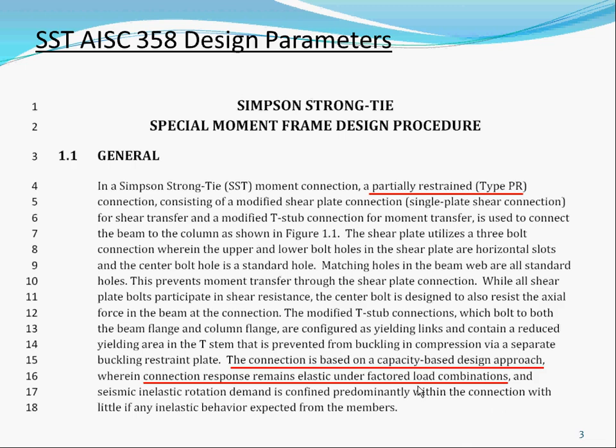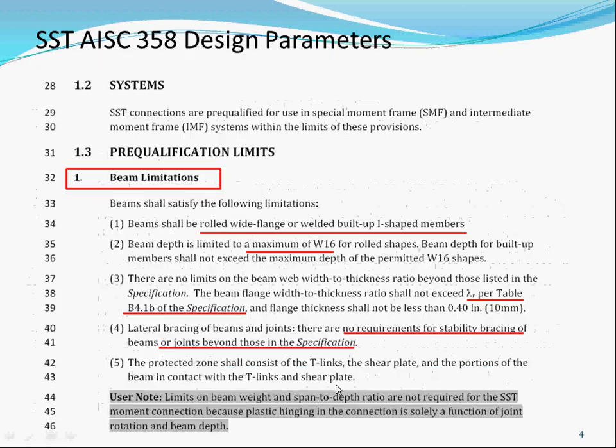And then the connection response remains elastic under factored load combinations. Factored load combination is what we call the load combinations. So the connection remains elastic, and we do not yield under those. That's why I go through some of the background first, so that when you read this document, you understand a little more what we mean by the different terms.